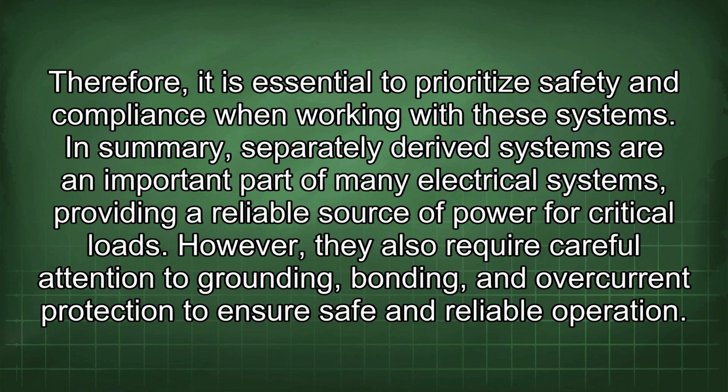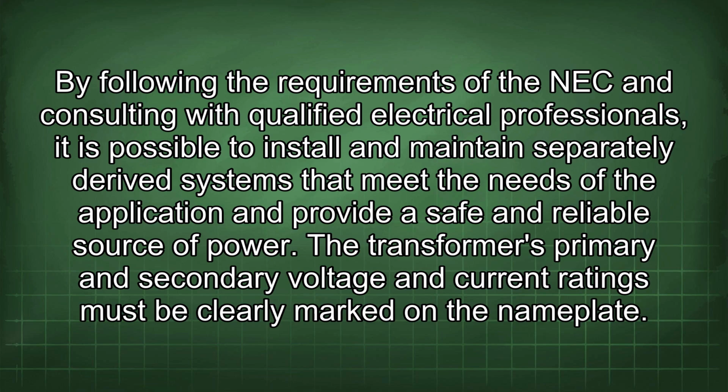In summary, separately derived systems are an important part of many electrical systems, providing a reliable source of power for critical loads. However, they also require careful attention to grounding, bonding, and overcurrent protection to ensure safe and reliable operation. By following the requirements of the NEC and consulting with qualified electrical professionals, it is possible to install and maintain separately derived systems that meet the needs of the application and provide a safe and reliable source of power.